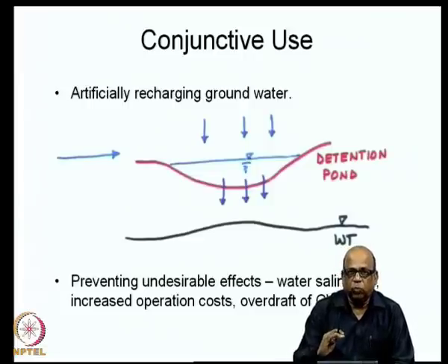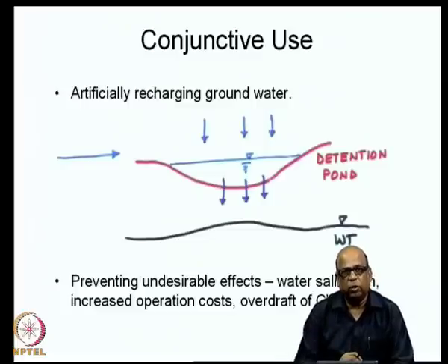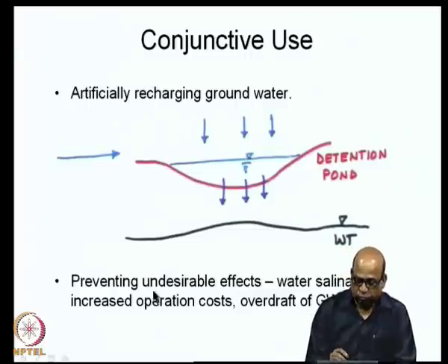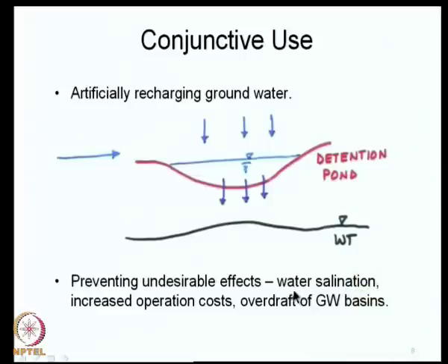And then the groundwater may enter into the root zone of the crops, because we are talking about the agriculture that is the irrigated agriculture. Once the groundwater enters the root zone, it causes salinity problems, water logging problems, etc., which affects the irrigation. And therefore, you need to manage the groundwater as well as the surface water systems, such that the ill effects are nullified or ill effects are taken care of. So, salination is one of the effects that you need to be alert.